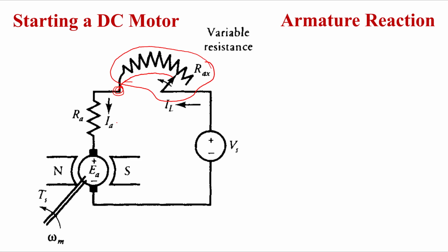So this is how we generally start DC motors. It is very important to put the rheostat in the armature circuit during starting, or we have a starter. You might have seen in your lab a starter with a handle. You have to move that handle gradually, so that means it is cutting the resistance gradually, from full resistance to zero resistance, and then it will come to the normal speed, right? So this is like a starter of the DC motor.